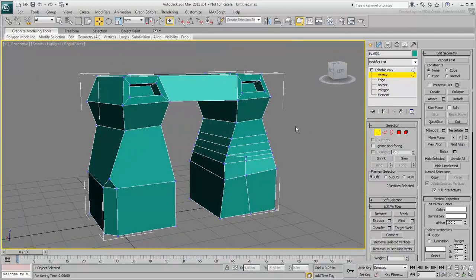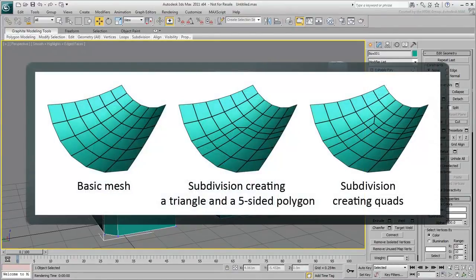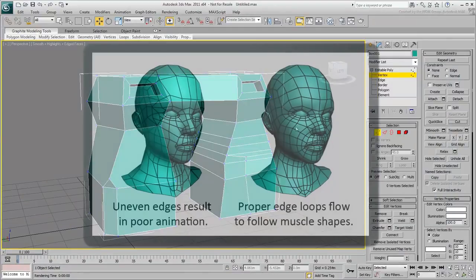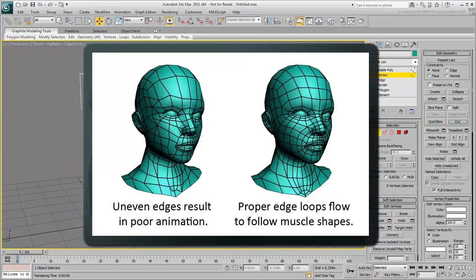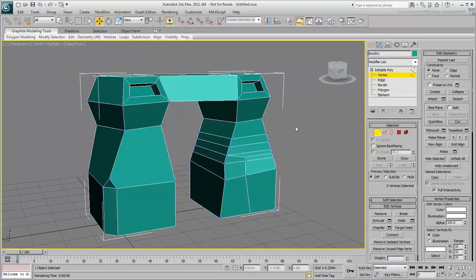As you model and subdivide, you want to control the smoothness of the surface. Here are some guidelines to keep in mind. When you subdivide polygons, it's important to create polygons with 4 sides, called quads, whenever possible. Create smoothly flowing edge loops in an even grid pattern. These guidelines are especially important when creating curved surfaces in areas that bend during animation. Otherwise, you can end up with unpredictable smoothing and smoothing artifacts such as bumps and holes. Creating an even mesh is also important for unwrapping, rigging, animating, and so on. Part 2 describes how to build a jerry can using the techniques shown in this movie.